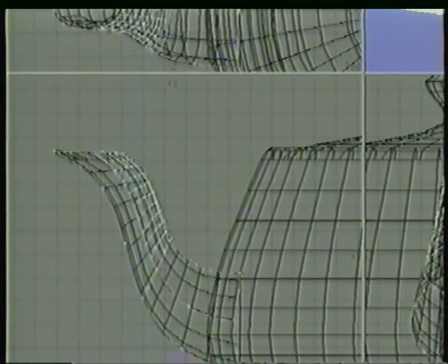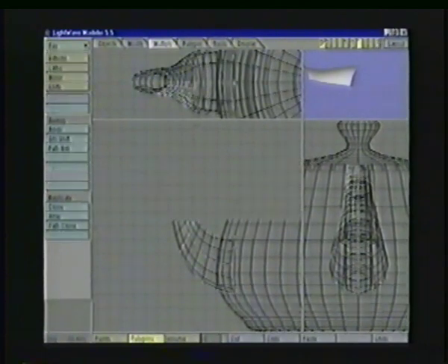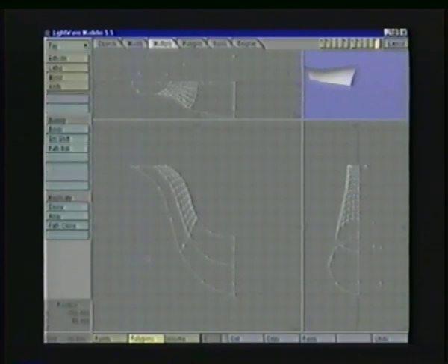One of the simplest is to make sure that when you patch, the patched polygon surfaces go into another layer. And there's a trick to doing that. I'm going to copy everything from this layer. I'm just going to hit copy, and nothing was selected, so therefore everything was affected. And I'm going to go all the way over to my right layer and click there. I'm going to paste this all back down. Now this is exactly what we had. I wasn't planning ahead very well because before I was in this layer and I had something in the layer next to it. What I want to do is make sure there's an empty layer to the left of the area where I'm spline patching.